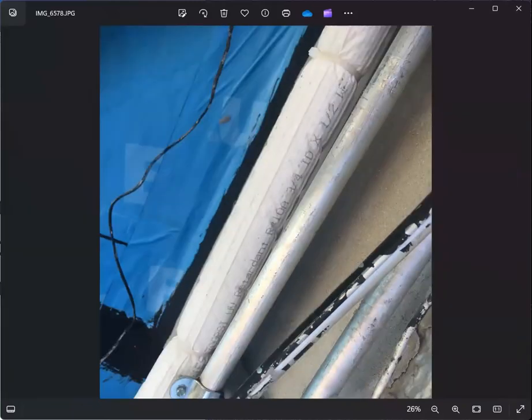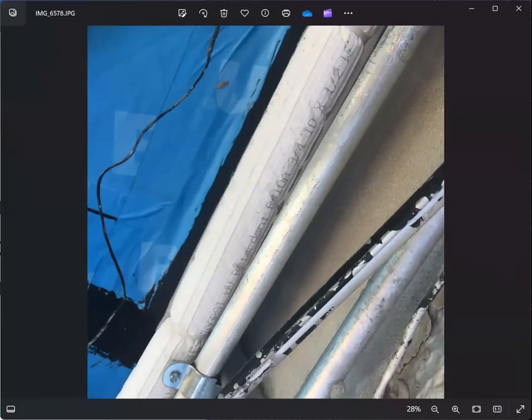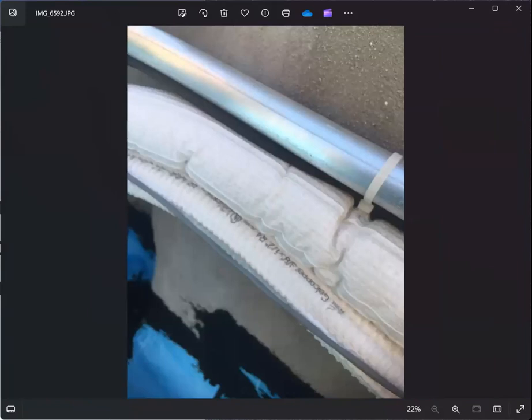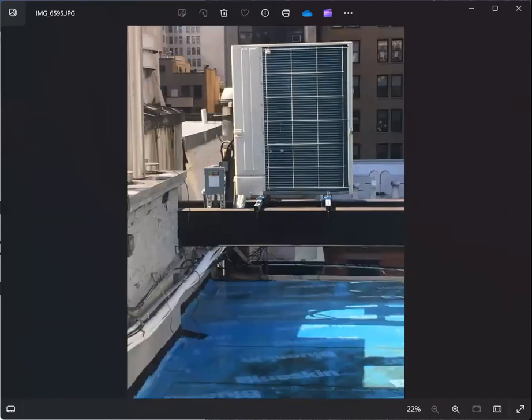Identify also the installation of the refrigerant piping line and take note, and ask for the submittals if it's approved for the installation. Probably it's like a package with the manufacturer of the fans, the ACs. So make sure that everything is documented. That's the main point.